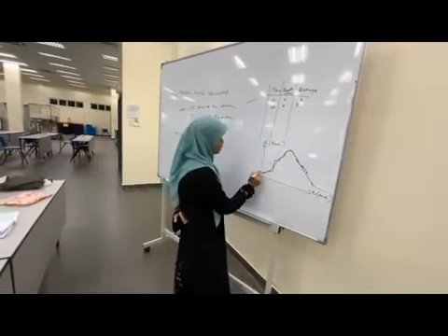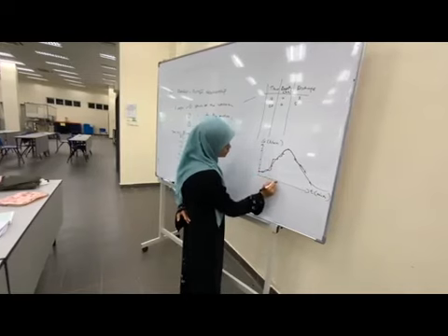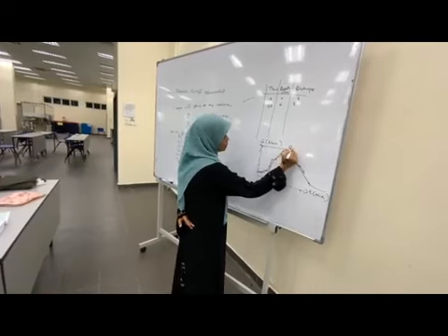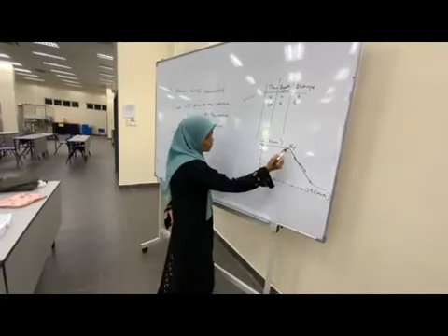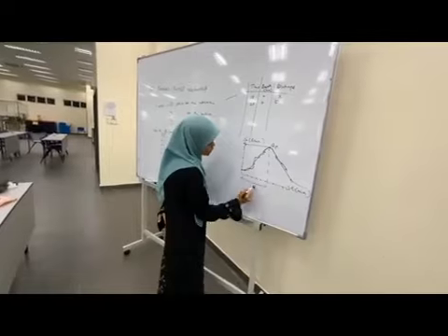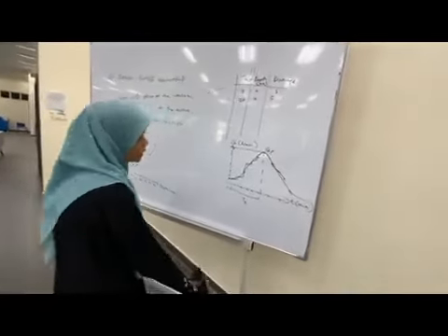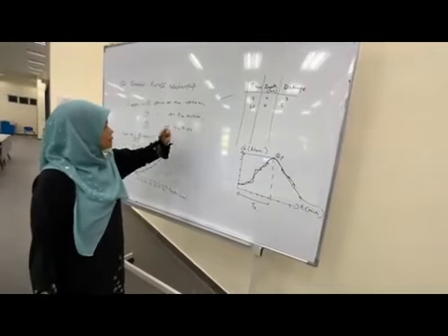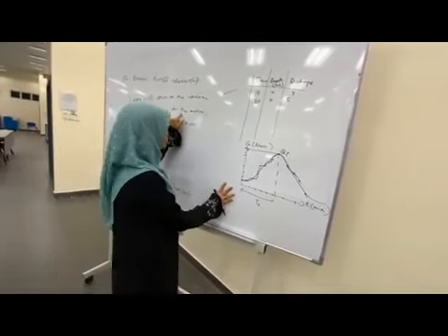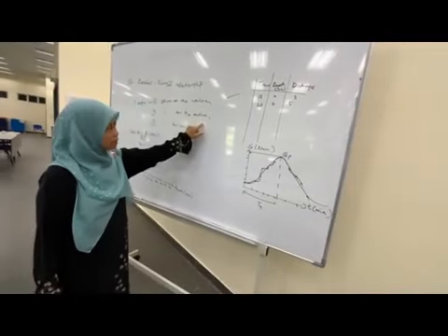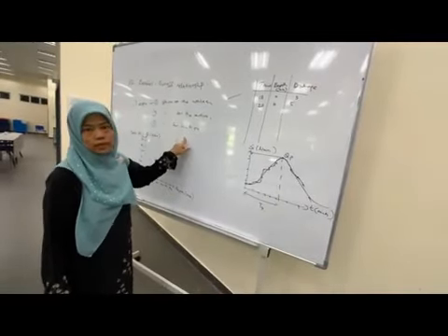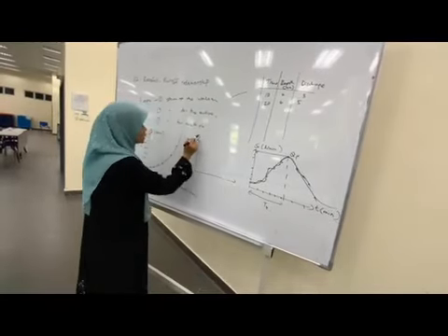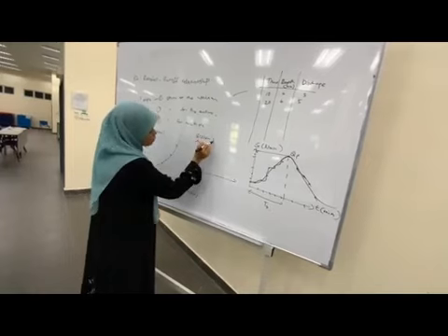From this hydrograph, for example, we will get the peak flow and the time to reach the peak. This one is for the upstream. Similarly, you need to plot the hydrograph for the entire catchment area and also for the multiple storms.